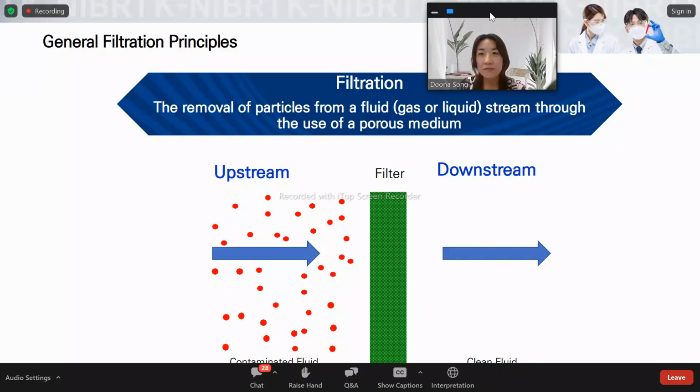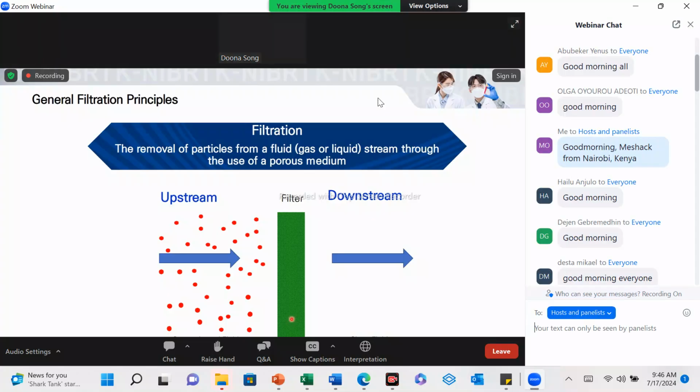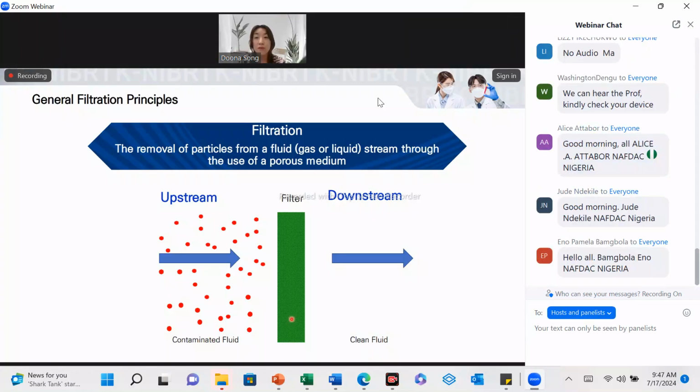One of the critical purification techniques is filtration. Essentially, it involves passing a particle-containing fluid through a filter membrane. Looking inside the membrane, you can see that it contains pores. Membranes containing different pore sizes are available for different applications. Particles larger than the pore size of the filter are retained by the filter, and particles smaller than the pore size of the filter pass through along with the liquid.